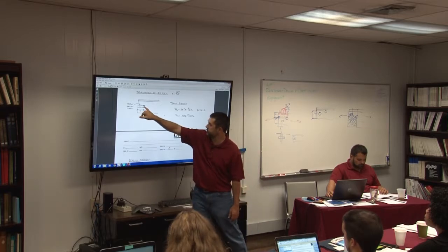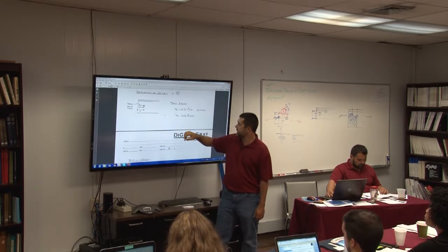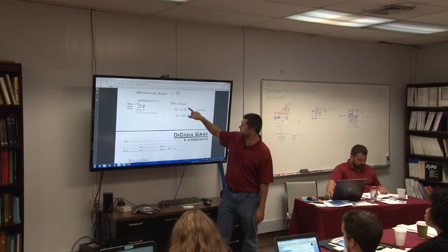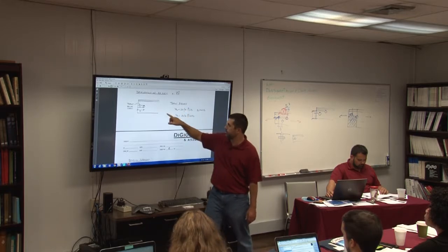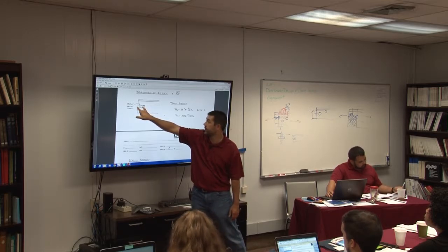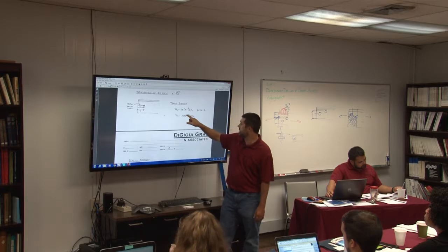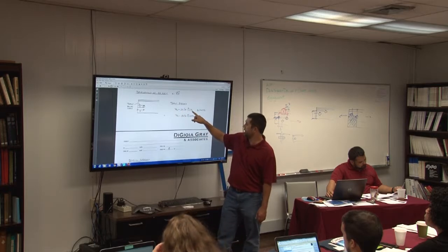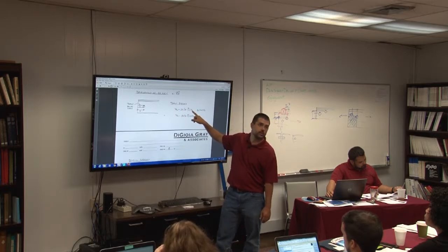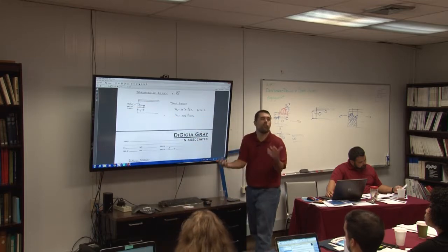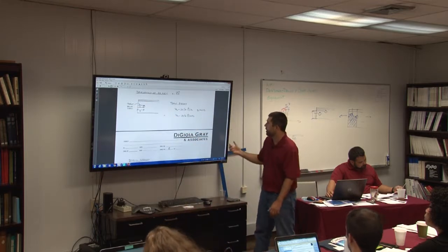If the end distance is from the center of the hole, I've got the end distance minus half of the bolt diameter. That gets me the approximate distance from the edge of the hole to the end of the member. I've got the thickness of the member times 2 failure surfaces, and then I've got a limiting shear stress. So that's like a shear failure across both of those planes. That's a different way to think about this tear out.